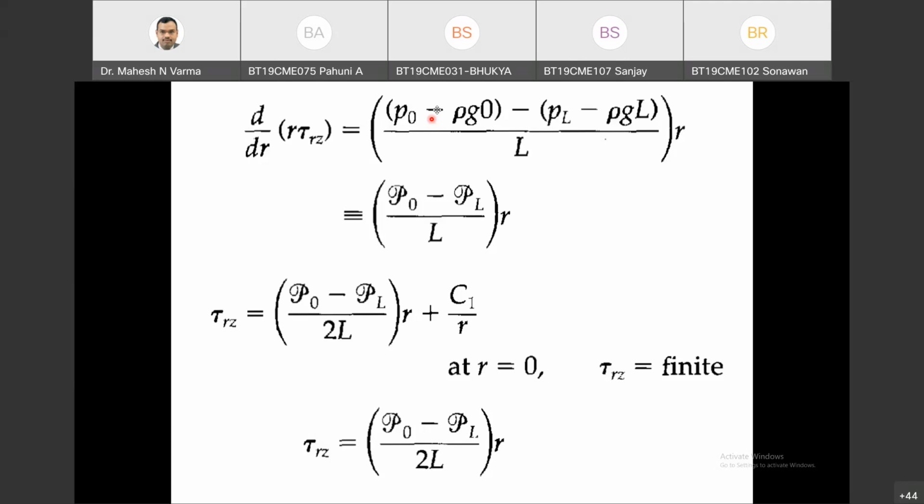And that indirectly we are telling laminar flow also. If you say the local value will change, then momentum will be transported in the other momentum direction. So it will violate the laminar flow definition actually. So it is a combination of all these things: laminar flow is there, the continuity equation is there, density is constant. Hence Vz is not a function of Z.